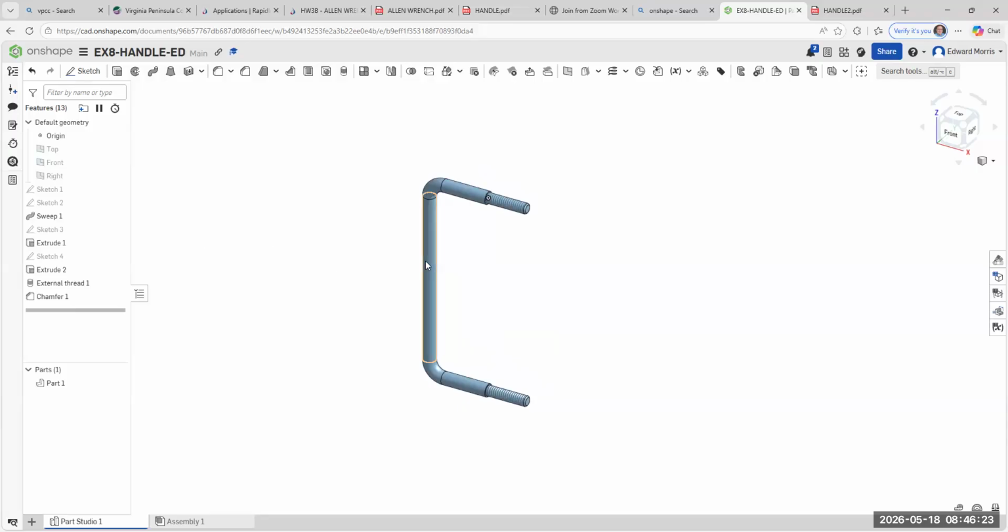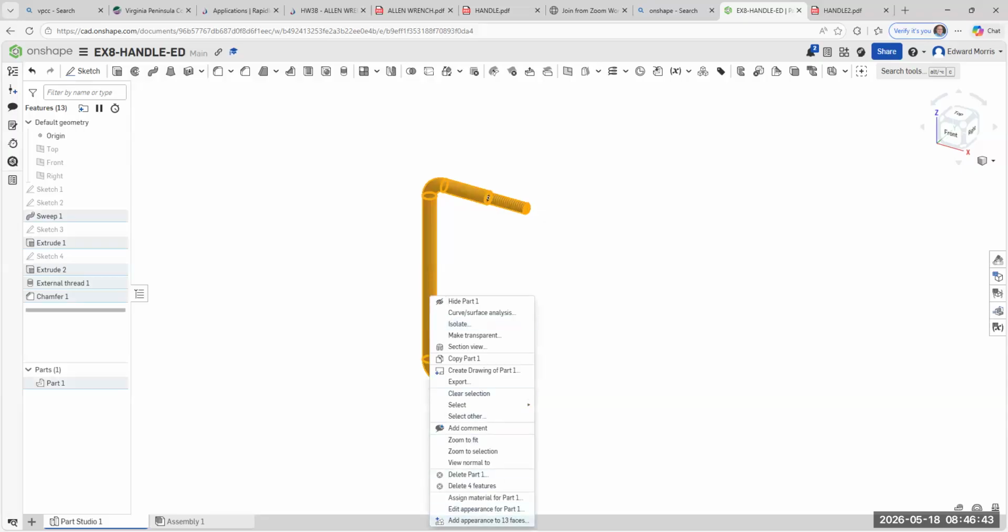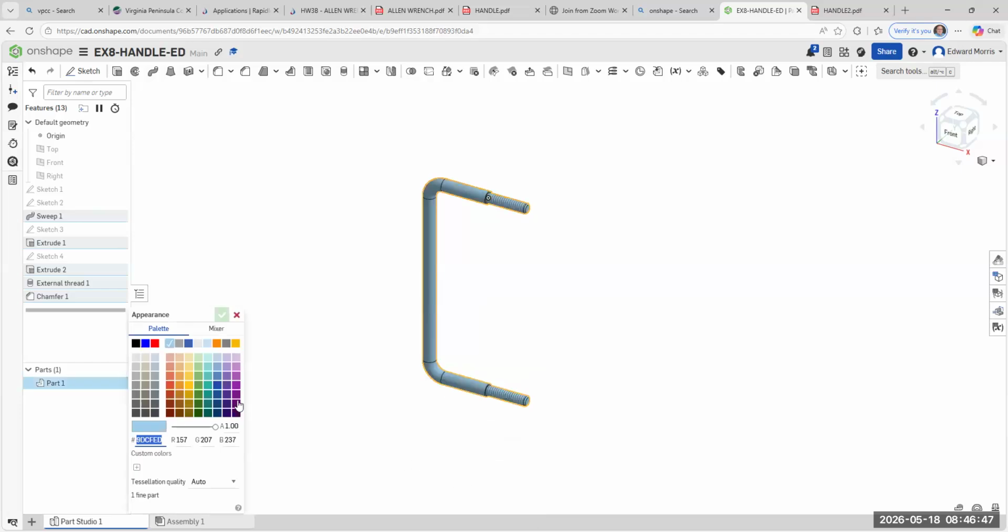And I'm going to right click on this. Actually, watch this. It's made into different segments, right? Watch very carefully. Hold down the left mouse button. I'm over here, right? And make a window around your geometry. Okay. Right click, edit the appearance of the part. And if you don't do that, it's only going to do the one segment, I think.